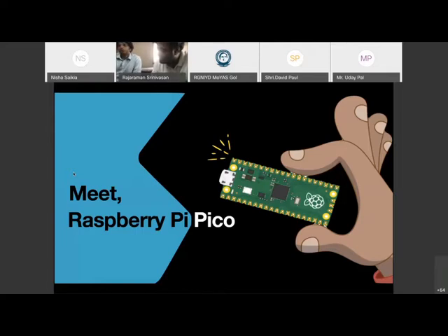The thing about Raspberry is previously they have been designing all of their single board computers with mostly Broadcom processors. They have been using BCM2835, BCM2836, BCM2711, etc. But those are all full-fledged desktop kind of things. The Pi Pico is a microcontroller, so that is why it is so special. And given its price, it has come to the top of all of the microcontrollers that we have. So we wanted to choose the latest and cost-effective one. That is why we are at Pico now.